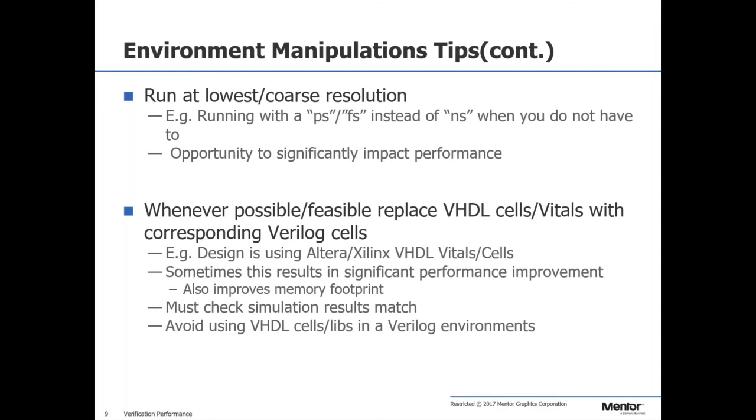On the other end of the spectrum, if you go too high on your resolution, then you will probably start to see that your test bench is not operating correctly. So for instance, I know for sure the Xilinx DCMs require at least 10 picosecond resolution. So if you're using a Xilinx DCM in your test bench, or in your design that's generating some clocks, then you have to go at least down to 10 picoseconds. So set it at the lowest you possibly can.